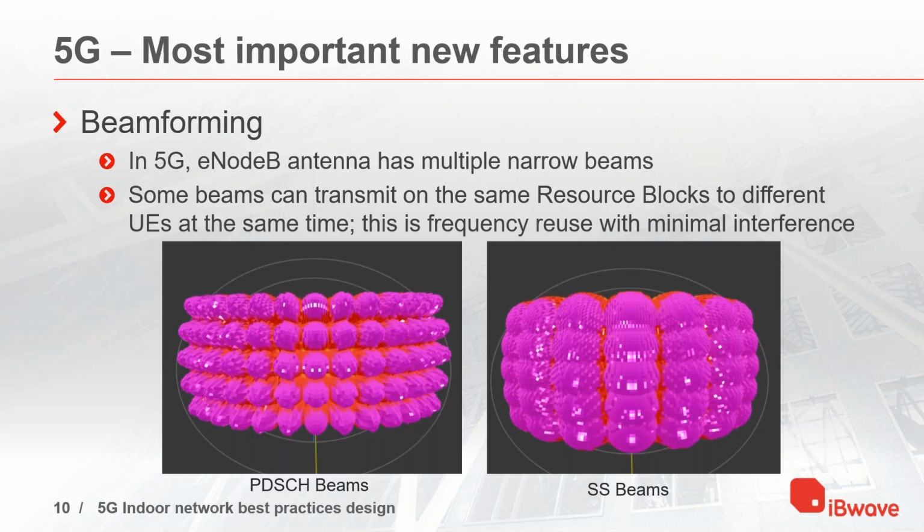There is something in every venue called a catwalk, very high up near the top of the arena. So you hang those small cells from the catwalk, and they point down. But you need to optimize where they're pointing, right? You want to point them to a certain section of the seating bowl below you, and to aim correctly, you will have to deploy the mechanical down tilt.